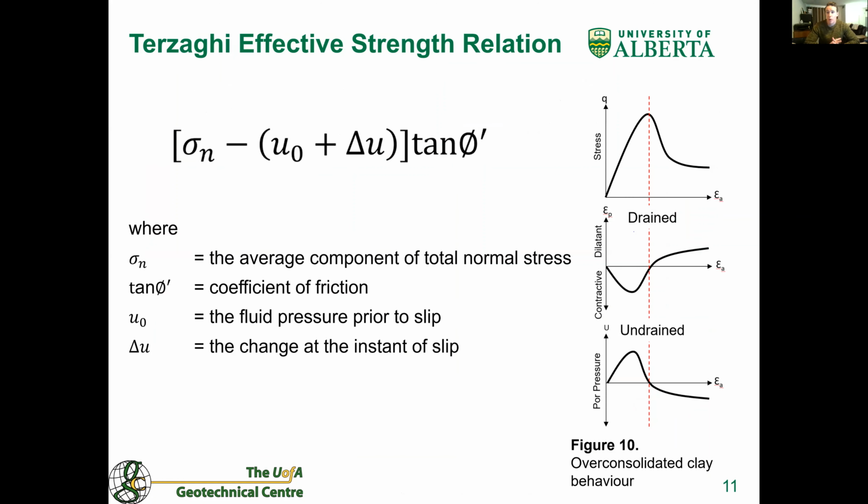These increases in pore pressures can potentially be explained by Terzaghi's effective strength relationship in 2 dimensions, or taken one step further and analyzed in 3-dimensional space using Biot's poroelasticity framework. Terzaghi's relation shown here is generally used to define frictional resistance for bedding plane stiffness.